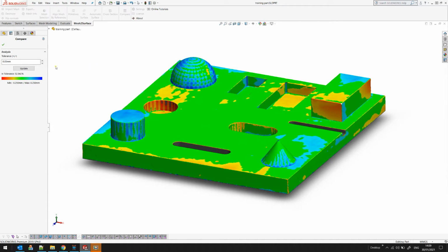The options we have here include what our zero tolerance is. We know that the scan data are always noisy. They are not perfectly flat or not perfectly cylindrical. That's why you need to have something which is acceptable for you. For example, in this case, you may want to work with 50 microns accuracy, or with 10 microns, and you can adjust these values and type in here.